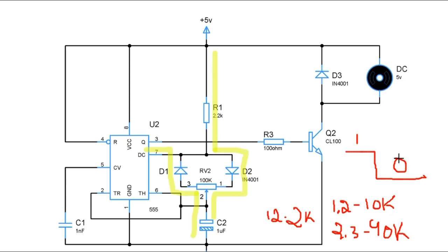So it implies that we can successfully modify the duty cycle to below 55%, which is the default criteria for an astable multivibrator using IC555. So it goes both ways. If you increase the resistance in the discharge path, it will yield a high duty cycle. If you increase the resistance in the charging path, it will yield a high duty cycle somewhere around 80 to 90, even up to 100% of the duty cycle, not exactly 100, close to 95, 97, somewhere around that.